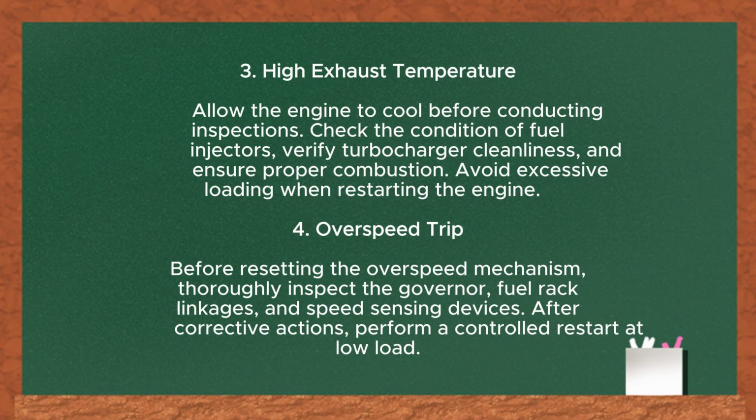Number 3. High exhaust temperature. Allow the engine to cool before conducting inspections. Check the condition of fuel injectors. Verify turbocharger cleanliness and ensure proper combustion. Avoid excessive loading when restarting the engine.